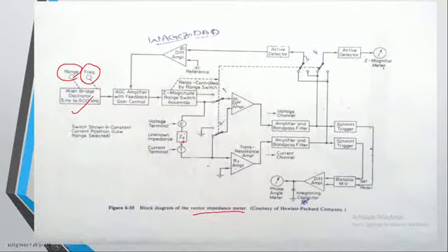After that we have the AC differential amplifier to measure the voltage drop across the unknown element, and we have two modes of operation. We'll come to that. We also have the AC transresistance amplifier, or simply a current-to-voltage amplifier, which converts the current at the input terminal into voltage by multiplying the input current with the resistance. Especially we are interested in the unknown component. It is a transresistance amplifier which simply translates the current into voltage form.